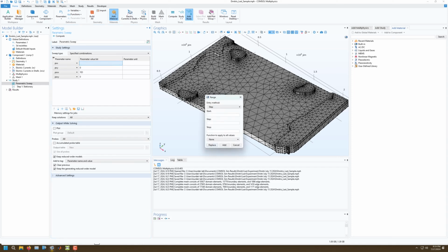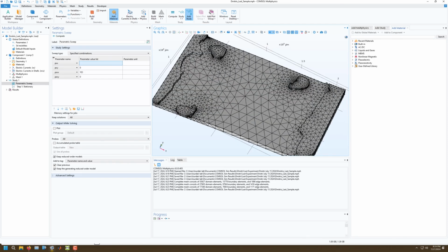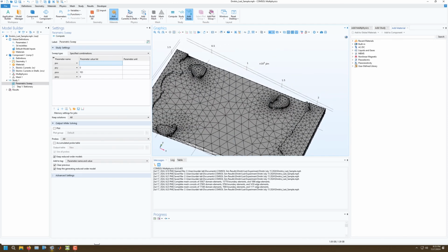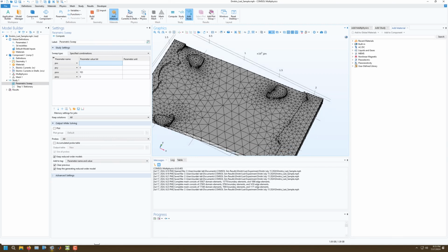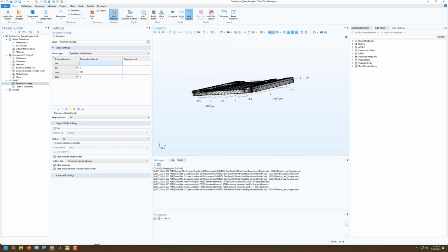So I'm going to vary U over a logarithmic sweep. Let's real quick, back of the envelope, calculate what the sheet resistivity is going to be. So the sheet resistance is resistivity times distance traveled divided by width. So the distance traveled between these 2 points. So the width is about 1,400, I believe.